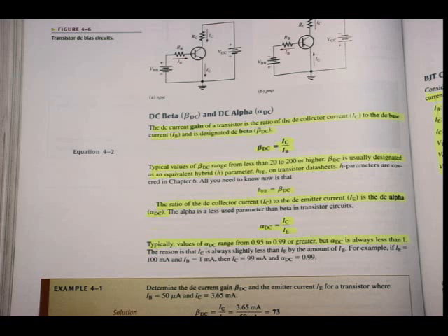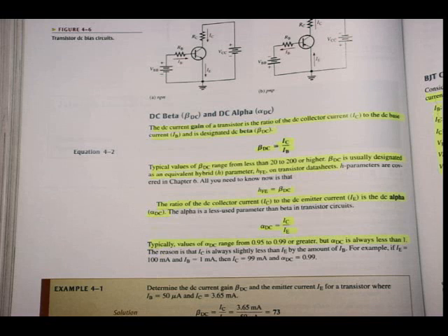But what I can see is that the value of beta DC is normally a large value. Why is it a large value? I can check it. What have I learned about the currents? I've learned that IE is the largest current because it adds IB and IC. But when we discussed the operation of a transistor, how does it amplify? What we've seen: emitter, highly doped, big; base material, thin, lightly doped. So what's going to happen? A little bit of recombination.